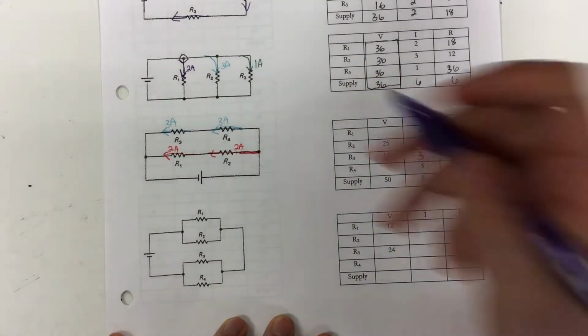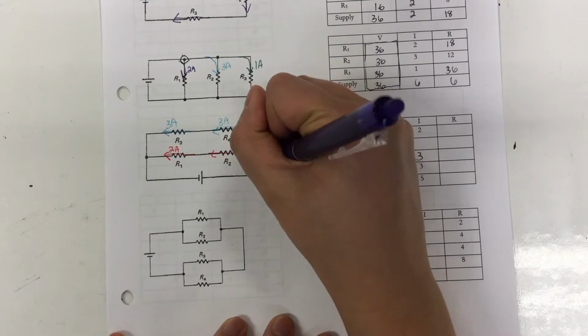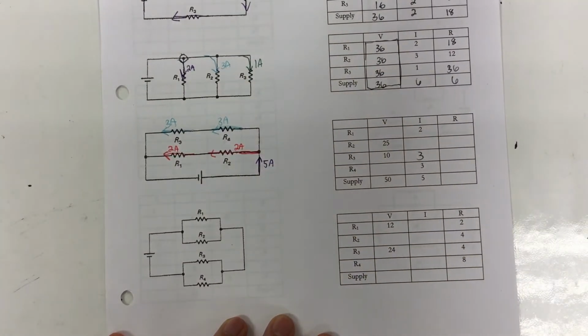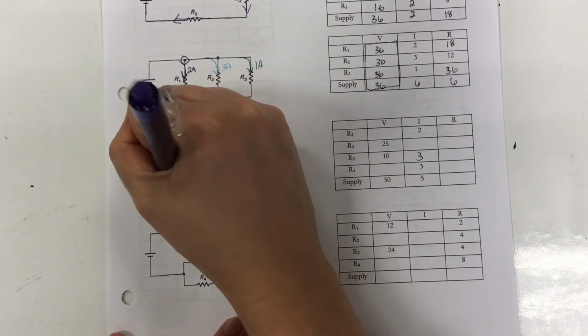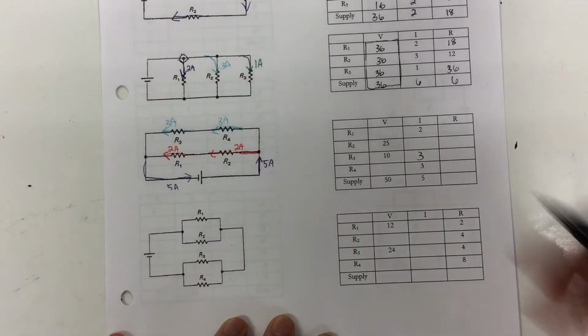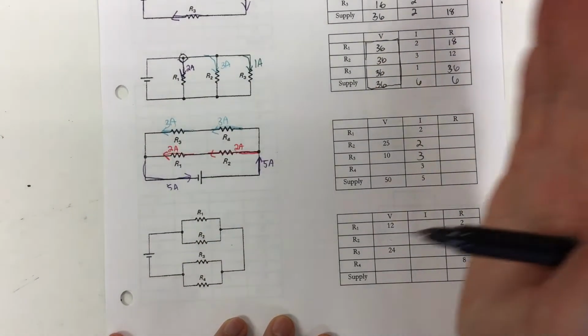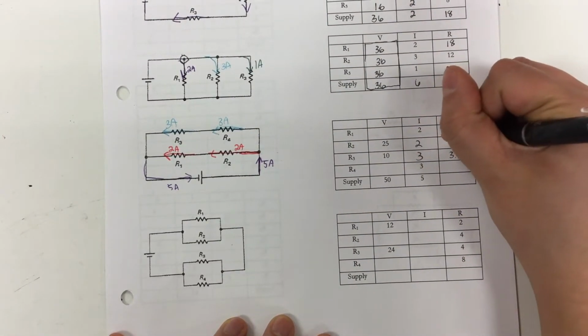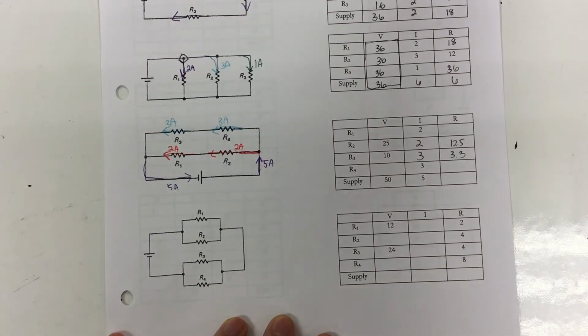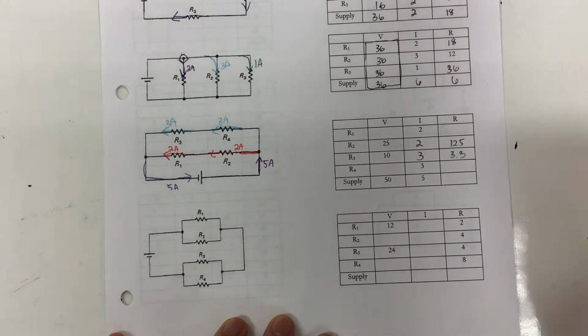And together that must have come from the battery. So 5 amps goes in, splits up along the 2 paths, and then 5 amps returns to the battery. So we've determined all the currents. We multiply out where we can. Now voltages.